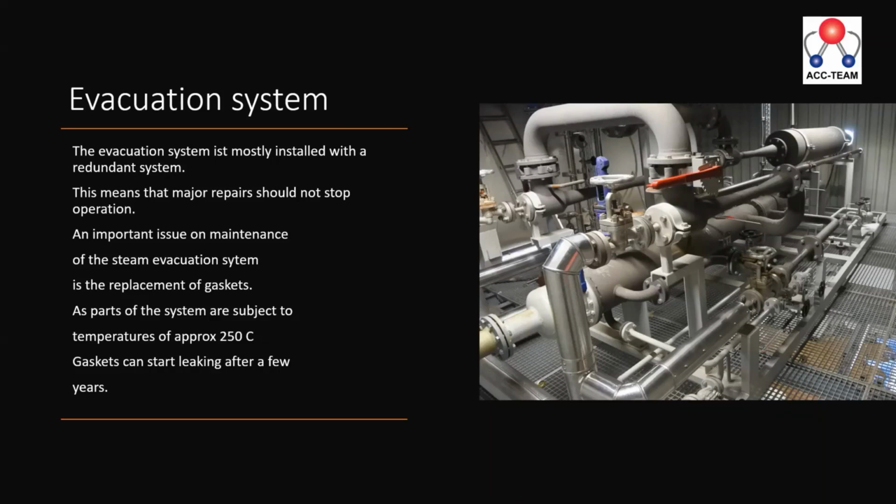Just a little example: it was a 750 megawatt power station in the UK, where I came around and saw that they could not achieve a back pressure below 135 millibar. So I asked them, what's going on? I said, your vacuum should be about 70. He said, yeah, we know, but it doesn't work. We actually have in operation all the vacuum units we have. I said, oh, hang on. So we went and had a look.